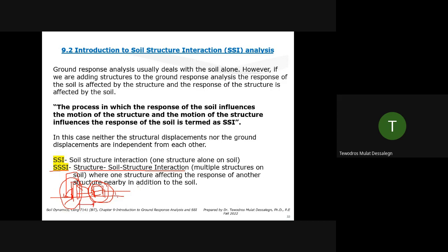If it's very far away, probably there is damping and the motion is not that much impacted by the presence of those two structures. So that was the part you asked me. If you have structures next to each other, there will be impact on each other. In my observation in the past, with a massive big structure next to a small structure, the small structure should consider the effect of the larger structure because there will be a big change. But when you analyze the big structure, you can ignore the small structure. The impact is negligible.